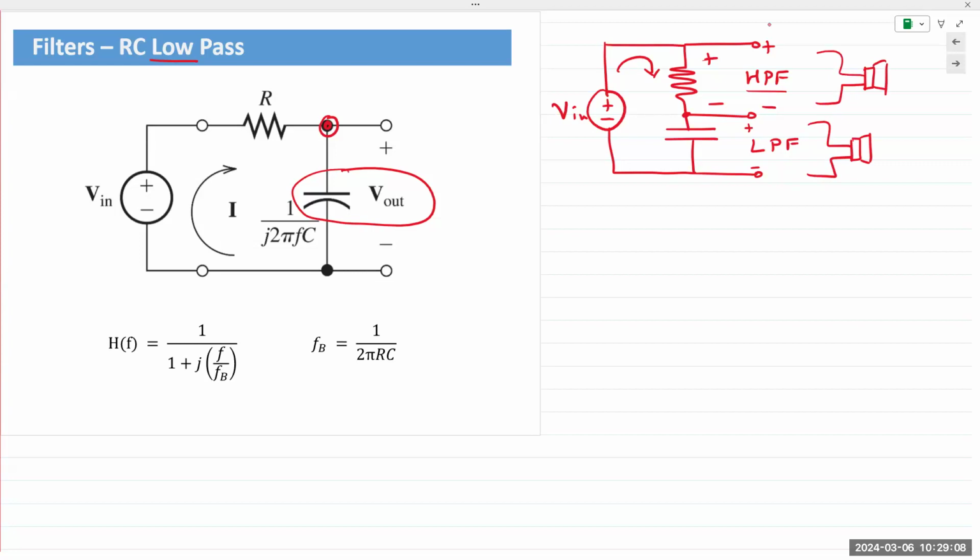Something like this right here, this is a two-way speaker, but it's a big box. So I would assume that it has a more expensive circuit inside it. Like the big professional speakers that we use for DJ audio systems, they have big crossover networks, inductors and resistors and capacitors. Much better filtering behavior. The cheap ones, if you have something lying around, you can just open it up and take a look at the back, and you will see that it will have just a resistor and a capacitor mounted on top.